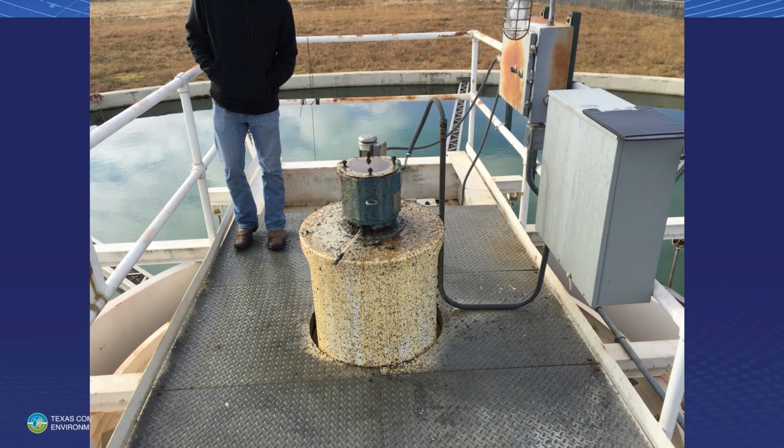I walked up on top of this clarifier and he said, oh, it's been working great. We love it. I walked up there and the motor that drives the recirculation fan underneath was gone. Gone. How long has this been gone? Oh, it burned out. We had to send it off. It's been gone about 6 months. Holy moly. 6 months with no internal slurry recirculation in a solids contact clarifier is definitely an issue.